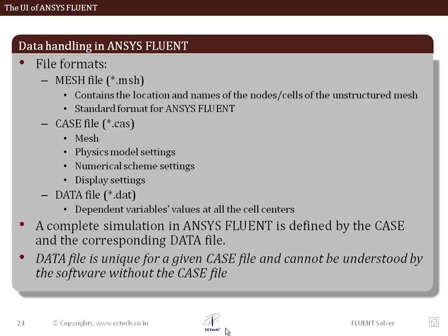It has to be accompanied together with a case file, and only then ANSYS Fluent can display to you the results, because it's the case file which contains ultimately the mesh file and the different physics settings. So let's say you generate a data file and you do not have the case file. You can mitigate this problem of the absence of a case file by just reading in the mesh file, and then that data is superimposed on each and every point which is available in the mesh.